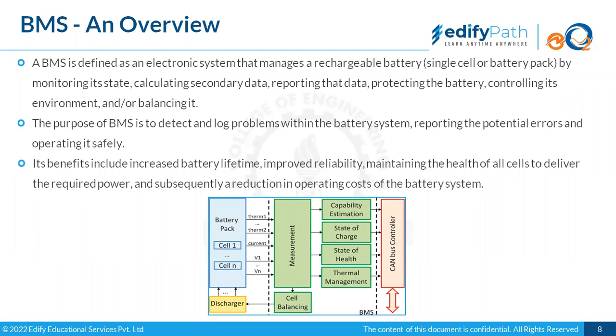So due to all these abnormalities, in case of an unbalancing of the battery, we have to take it to the service center so that it gets balanced again. In balancing, they would assure that every cell and every module is at the same voltage, so that during charging and discharging, an equal amount of current is flowing through them, or when charging, they are accepting an equal amount of current.